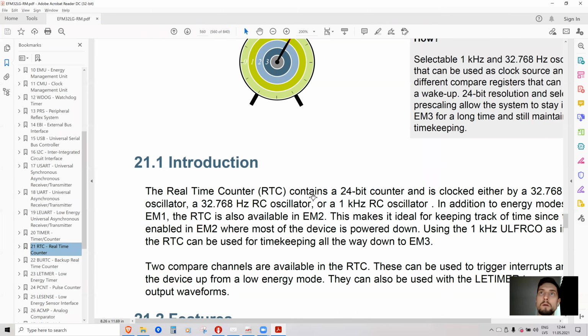Then we need to make this initialization structure, RTC_Init_TypeDef myRtcSettings equals curly braces open and closed. I control click on this thing. Here's the RTC init defaults. I copy these defaults and I paste them here, and then I check out what these settings do.